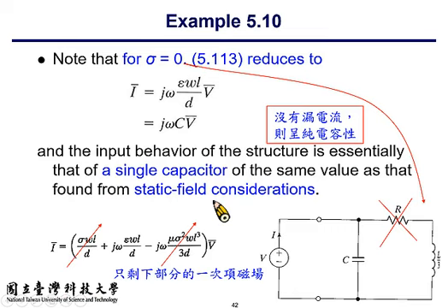And this result suggests that at a very low frequency, the circuit, the parallel plate capacitor, shall behave like a capacitor. Nevertheless, as the frequency increases, at a higher frequency, the inductive property of the circuit will also appear and dominate. So at a sufficiently large frequency, the circuit itself shall behave like an inductor instead of a capacitor.